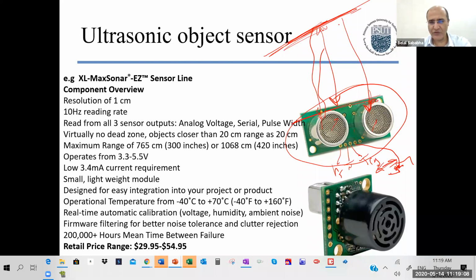So if you want, you can do it by reading data sheets, or you can just easily connect this to a scope and measure the time it took since you gave a signal here to come high back. Measure the time and see how this time is dependent on the distance in front of the robot.